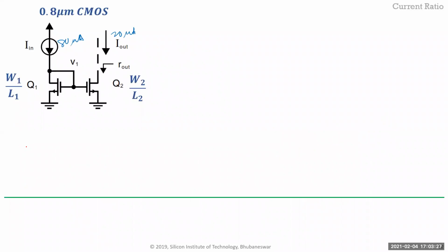So, current ratios. As I said, if you have one current source, so you have a 10 microamp current, one circuit might be wanting 10, another might be wanting 8, another might be wanting 20, another 100. So they're wanting different amounts of current, right? So how do you provide that from the same master current? Like I said, you can just keep copying it. So you say, I'm just going to create 10 of them. Whoever wants 20, I'll put two of them in parallel.